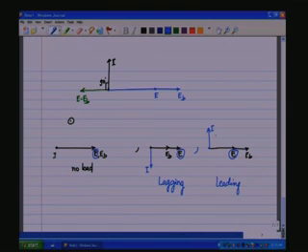Here the input current is leading the input voltage. By adjusting the value of EB anywhere in between these 2 points, we can get different lead and lag angles of the input current.